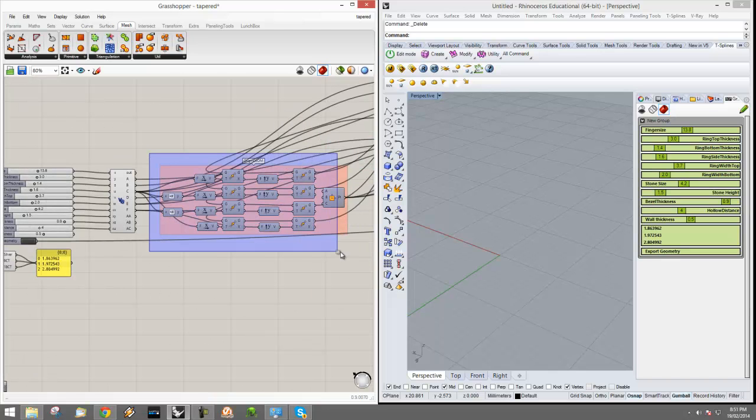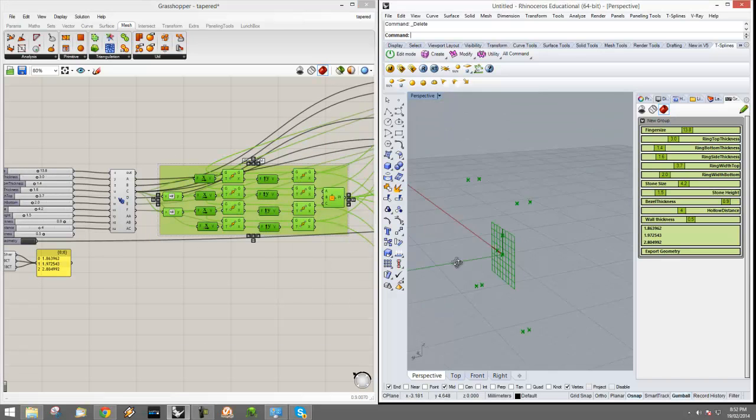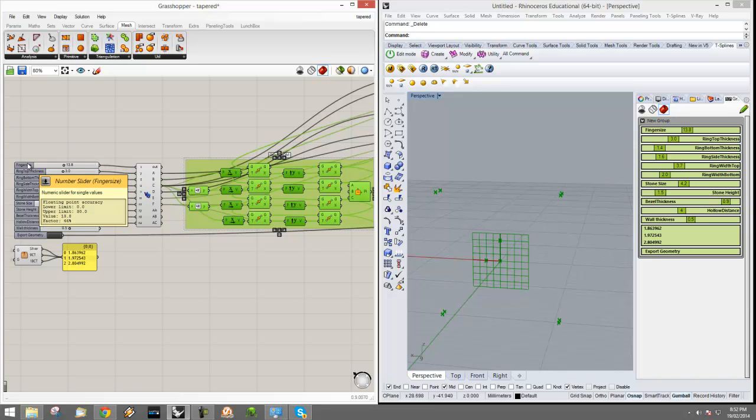If I show you all of these items, if I make them visible, you can see what I've done. I've started by creating a plane in the background, giving it 4 X and Y points. I've created the points which are over there. I've moved them to specific areas based on the relative size of my ring. So I have a minimum X and Y in the finger size in terms of left to right, up and down. But then I also have, over the finger size, a ring thickness, which is up here. So in the VB code here, there's this plus this offset by the width becomes that point. The finger size plus the width becomes that point over there, that point over there, that point. So I've got the 4 points over here.